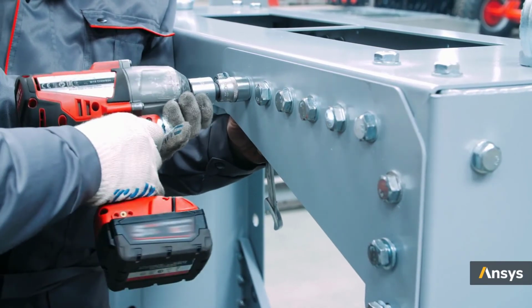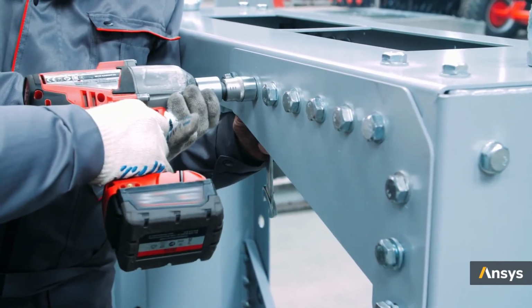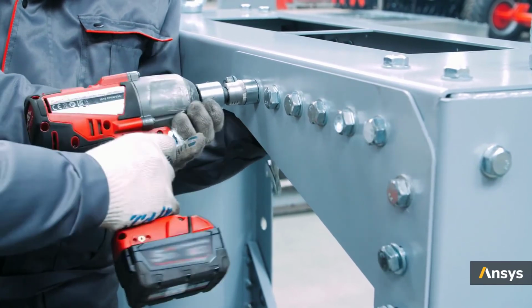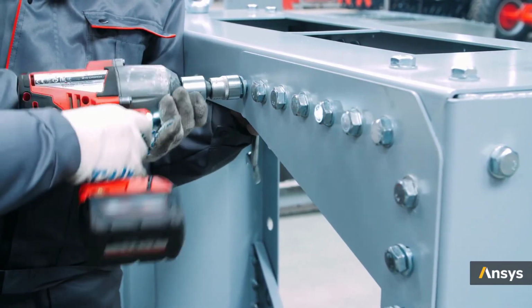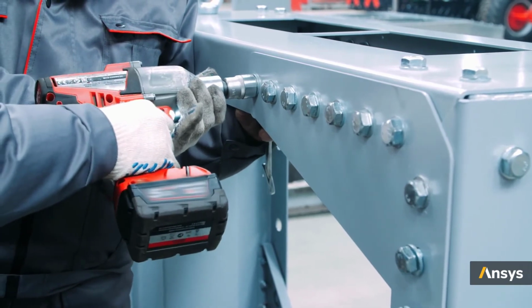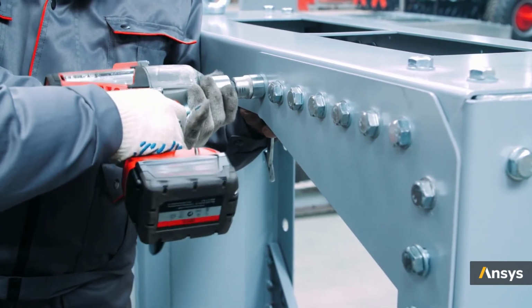But when the same two parts are held together by a bolted plate mechanism, then the surfaces can slide over each other to a small degree. Even this small motion can make the system nonlinear. Having said that, if this bolted joint happens to be part of a huge assembly where small relative motion between the parts is irrelevant, then it can be idealized as a linear contact. So the analyst must first determine whether this detail is important for their study, and based on that, plan on whether the contact should be nonlinear.